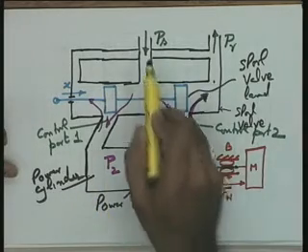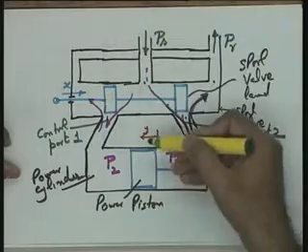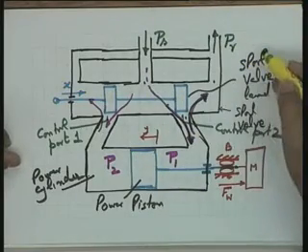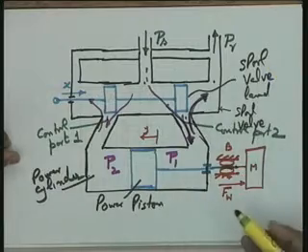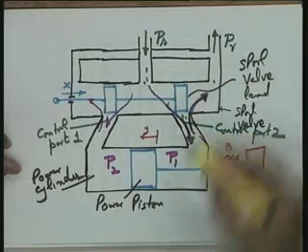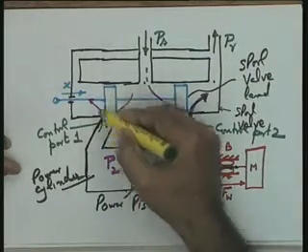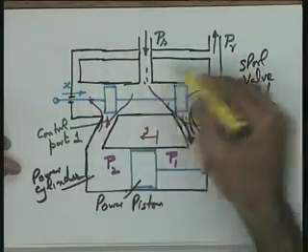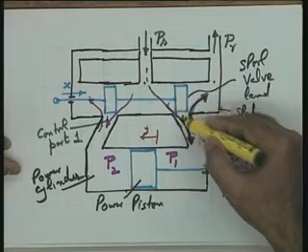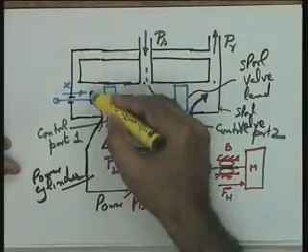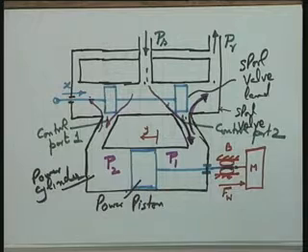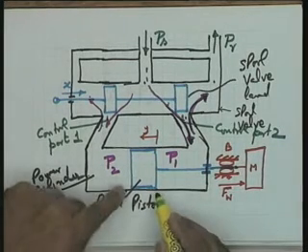You see that the net pressure difference, the fluid entering is at Ps, the fluid going out is at Pr. The net pressure difference is Ps minus Pr. Account for that. This is a drop over here, there is a drop over here, and there is a drop over here. So, if you travel through this particular route, the net pressure difference is going to be equal to this drop plus this drop plus this drop. It means the supply pressure. This is obvious. Please see that the supply pressure has to account for the pressure across the power piston.